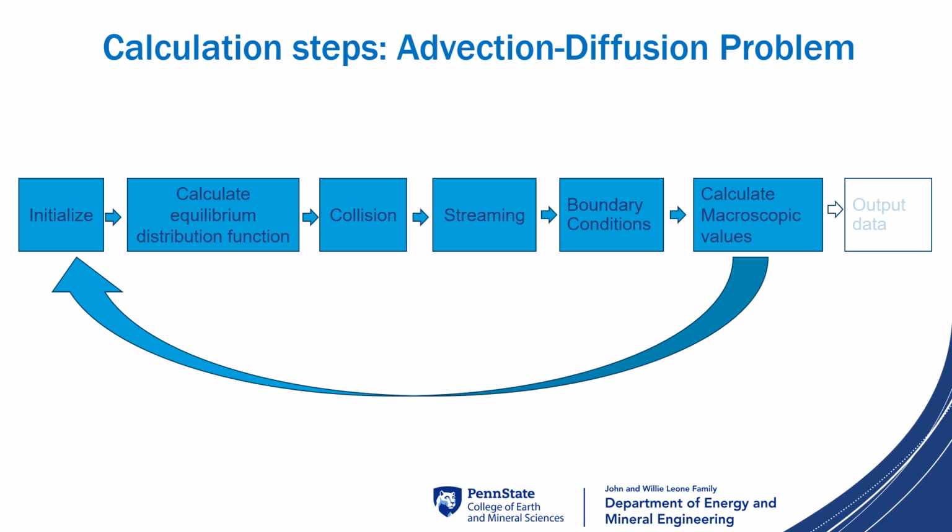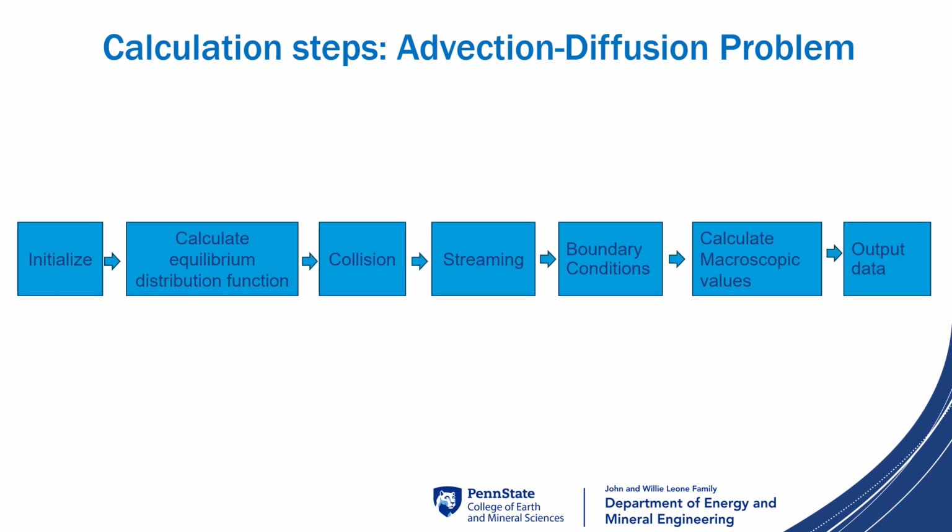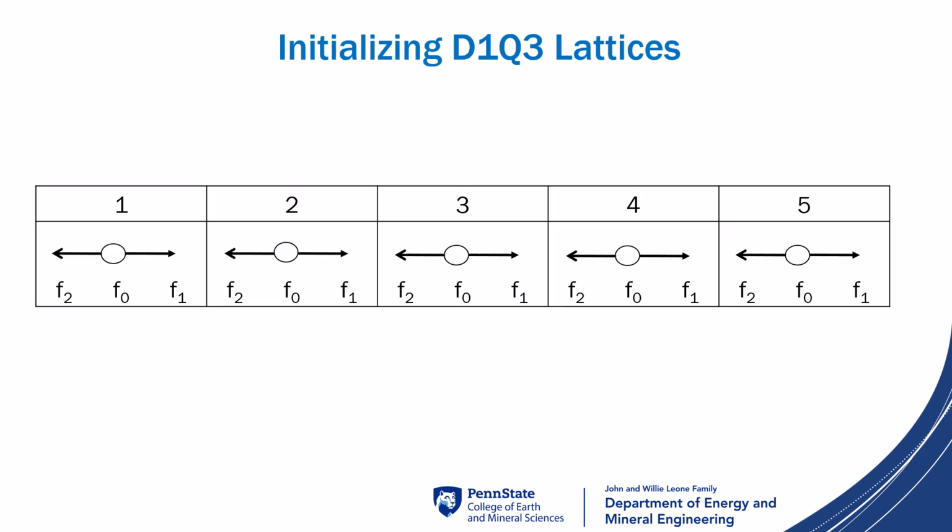We'll repeat this full loop for each hour in the hand calculation, updating values step by step across all 5 nodes. Because everything is local and rule-based, it's possible to carry out the entire process by hand while still capturing key physical effects like diffusion and advection. Our final output for our hand calculation will be the temperature across a 5-meter channel after 4 hours.